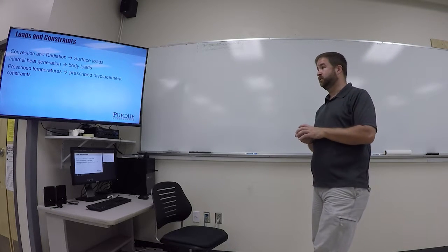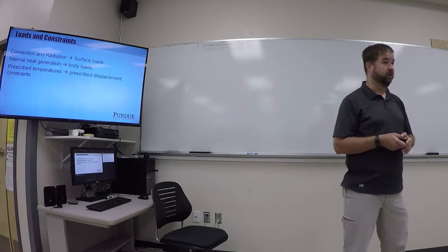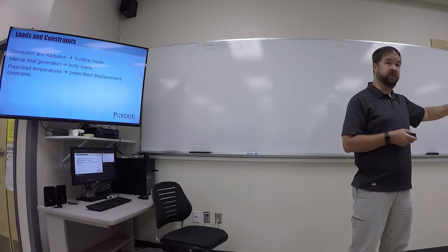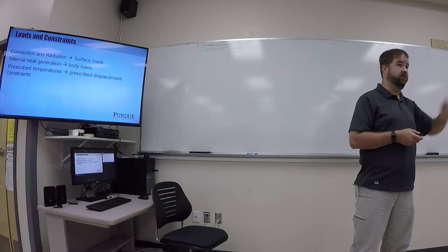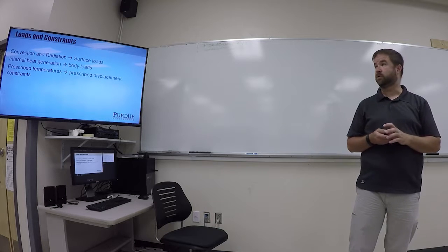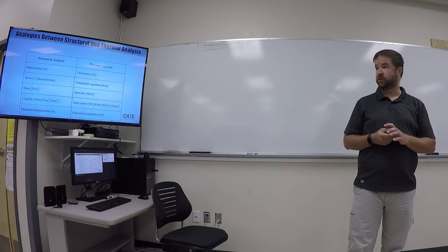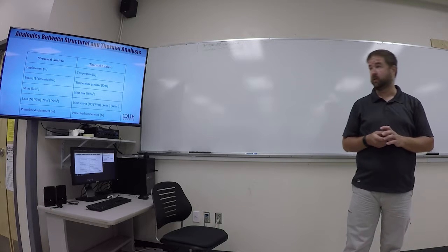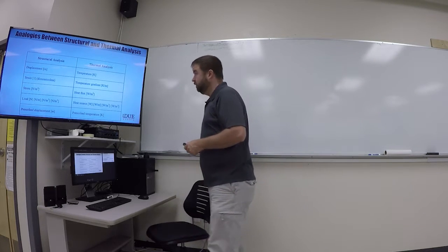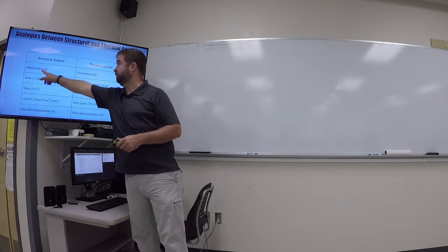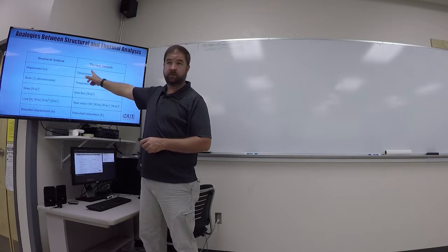And then we can do things like prescribed temperatures, similar to saying that we're going to deflect an inch at the end of this beam. You can say, well, it's going to have a temperature change of some amount at the end of the structure. So I put together a table that shows the things that are related to each other, structural analysis versus thermal analysis. So in structural analysis, displacement is equivalent to the temperatures in a thermal analysis.